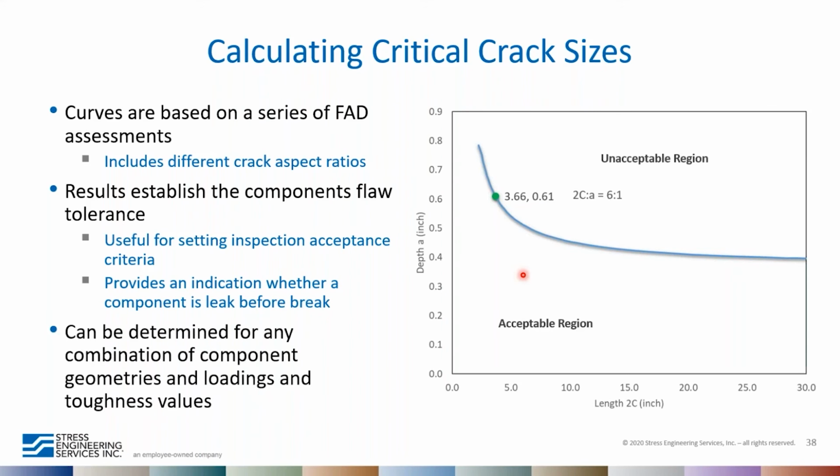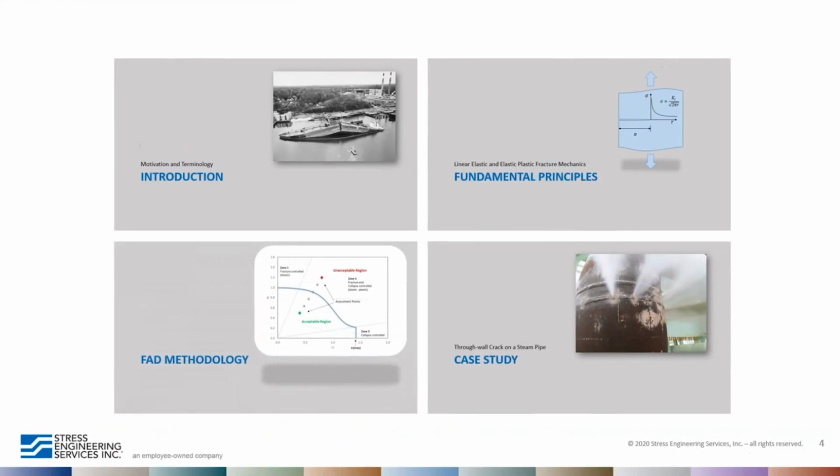Okay, so these critical curves can be determined for any combination of component geometry, loading, and toughness values, and at the end of the day, it represents a solution about the condition of cracks in the component.